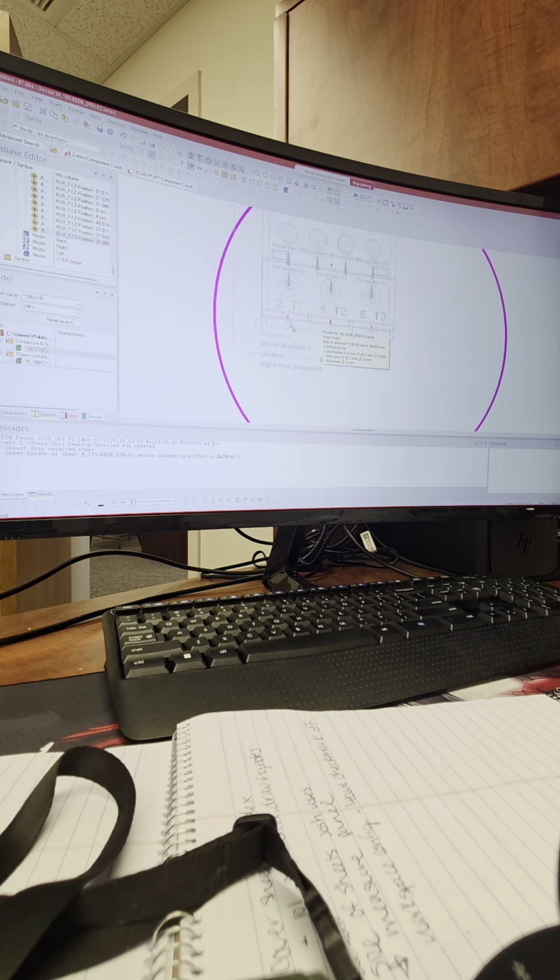Okay, so in this case, it looks like each contact has a slot point. This could be used for jumpers. It could be used for combs, as in mechanical combs, to combine multiple of these starters, like T1 to the next T1 to the next T1 together. Also, your starter, for example, could be one of those contact points, as in, technically speaking, you could add this auxiliary contact that we were just looking at into T2 and T3, meaning all of these individual points are possible insertion points for something else electrical, like another expansion of something else.